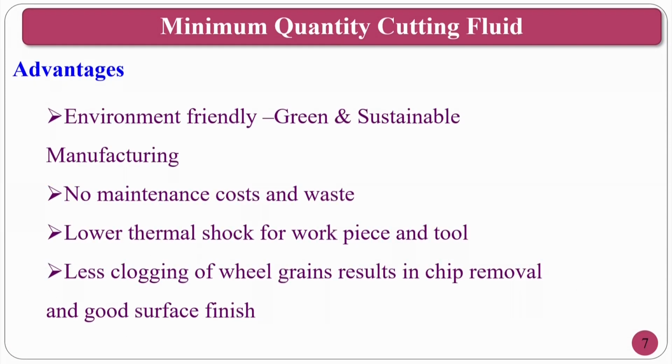So the minimum quantity cutting fluid advantages: it is environmentally friendly, with a green and sustainable manufacturing process, no maintenance cost and no waste, because it is just a spray that you spray and it goes off. So there is no recycling process, no transportation, no post-treatment of disposals and all those things. Lower thermal shocking for the workpiece material, because thermal cooling will take place by forced convection.